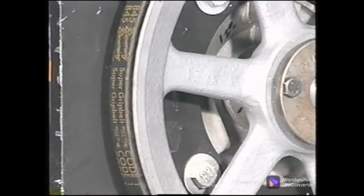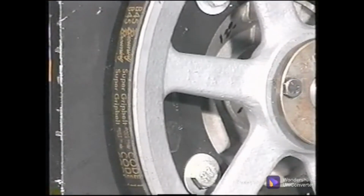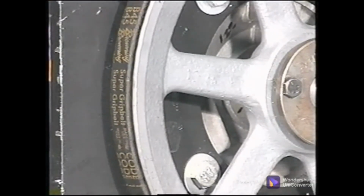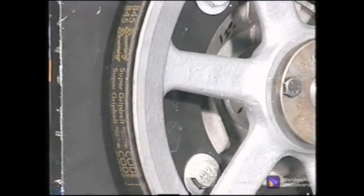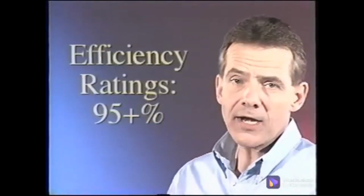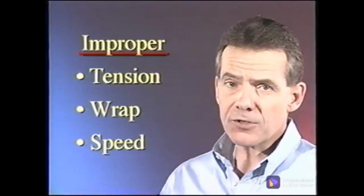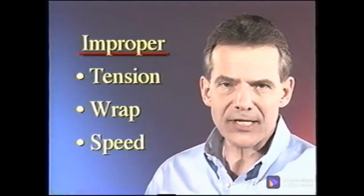For example, as the belt rotates faster, centrifugal force pulls outward on the belt, pulling it away from the sheaves and increasing the possibility of belt slip. Belt drives can be very efficient, with efficiency ratings above 95%. But improper tension, belt wrap, and speed can reduce the friction and severely reduce the efficiency.